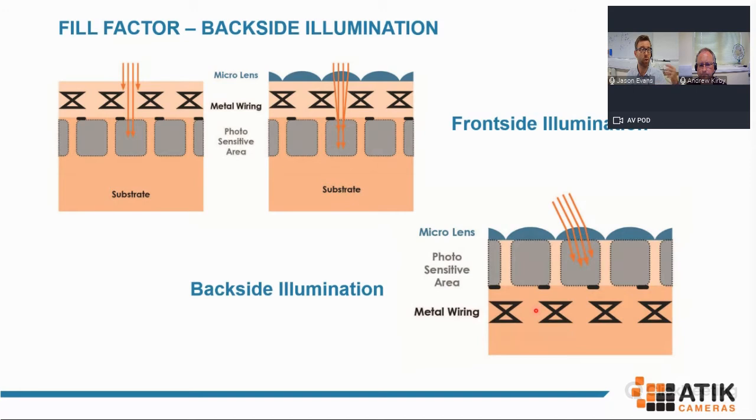If you've got certain areas which are likely to be quite bright, then they might fill up those wells a bit faster. As a result, if you want to have definition between much brighter and much darker areas on your image, you might want quite a large well depth to capture both of those during an image. So it's not necessarily important to all customers. Certainly if you're doing shorter exposures or working at really, really low light levels, modest well depths might be of more interest.